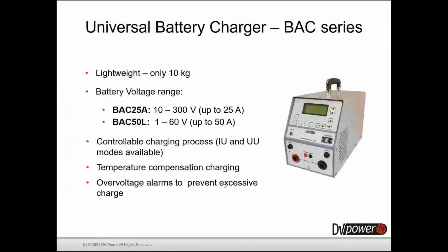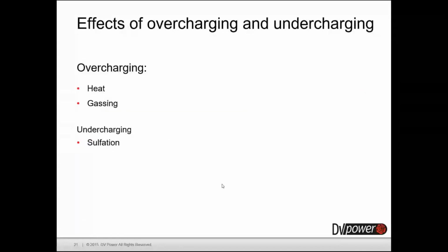So, as can be seen in this presentation, the charging procedures are different depending on the battery chemistry, which is completely in contrast to the discharging process, because the discharging process is pretty much the same for all types of chemistries, but the charging process is different, and that's why it is even more important to follow the manufacturer's recommendation during the charging process than for the discharging process.